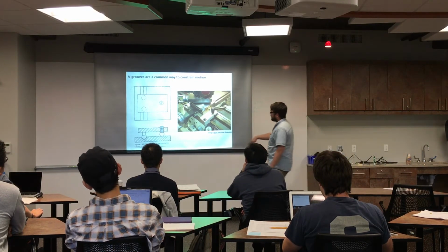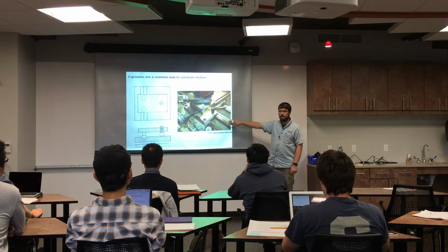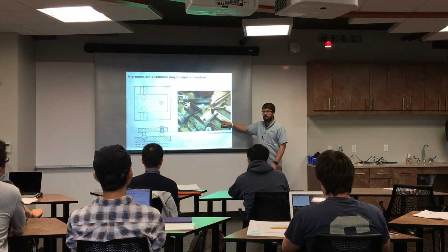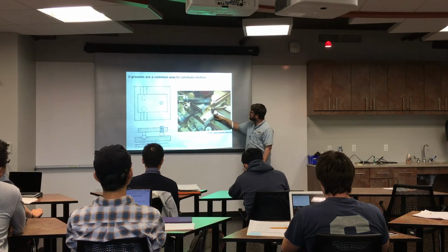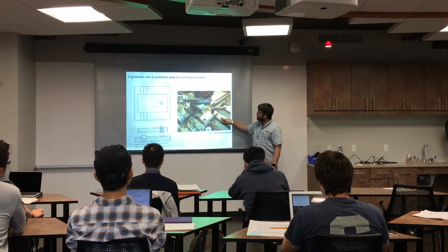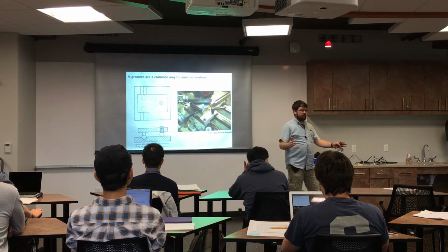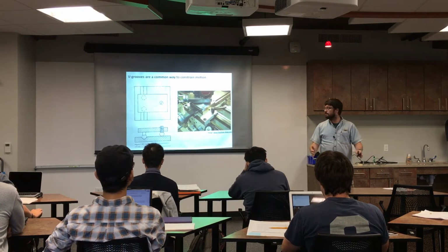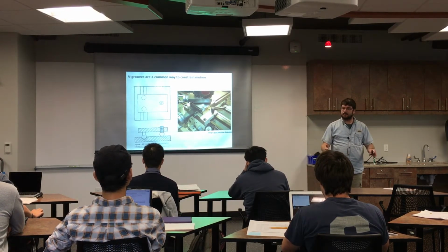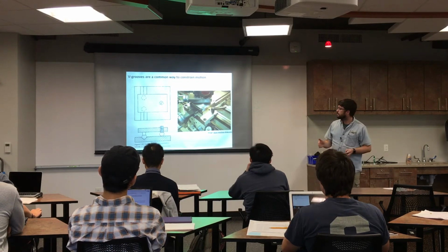So if you look at the bed of a lathe, like we saw over at the shop, you would see that they're called the ways of the lathe, these inverted V in this case, where the carriage travels along. So that constrains the carriage. It can't move side to side. It can't move up and down. It's clamped, really. So it can just move in one direction.